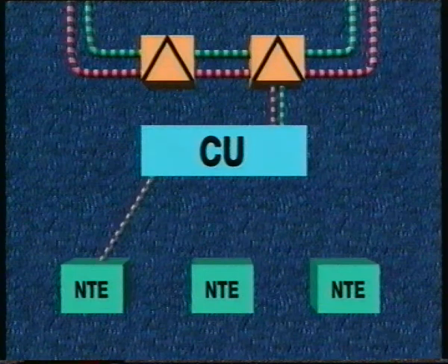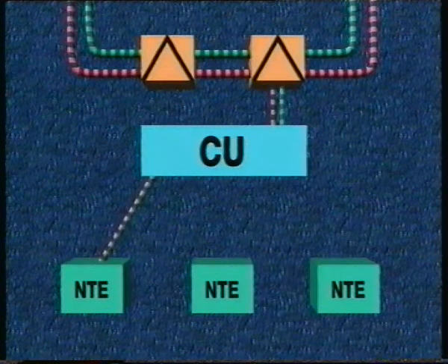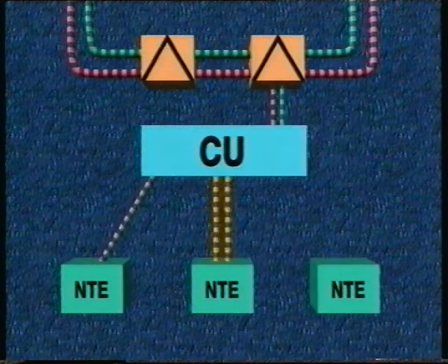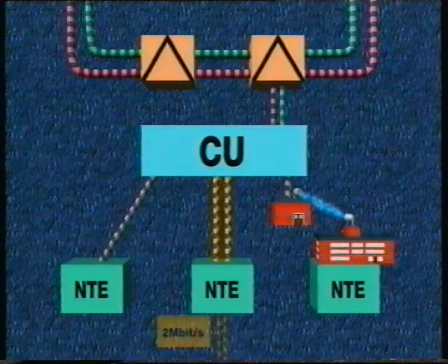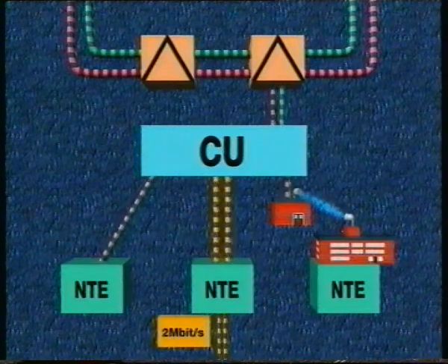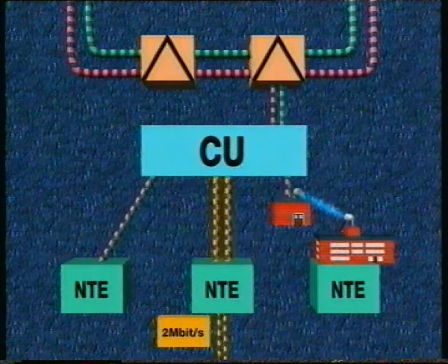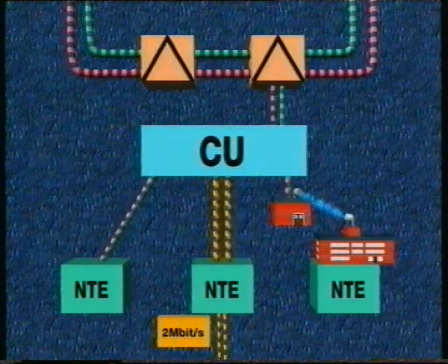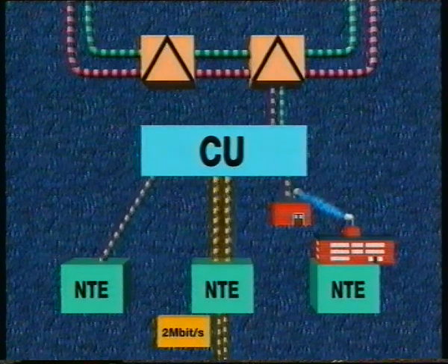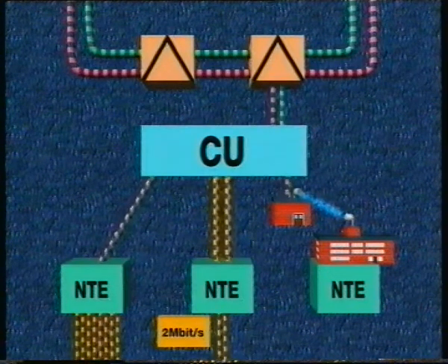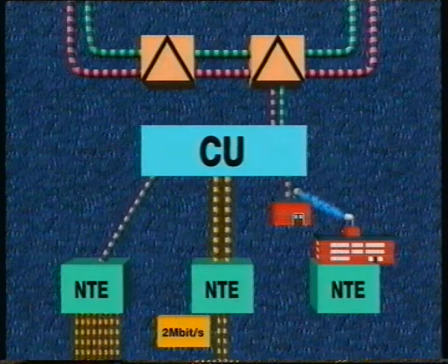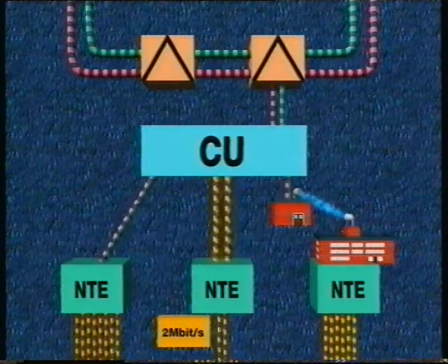This connection is normally achieved using a single optical fibre, but can also be copper or, in the near future, radio. Copper delivery requires two pairs to provide a single 2 megabit circuit and utilises high-density subscriber loop technology, or HDSL for short. As you'll see shortly, there's a range of NTEs, and these provide the customer with the service interface such as G703 and X21.